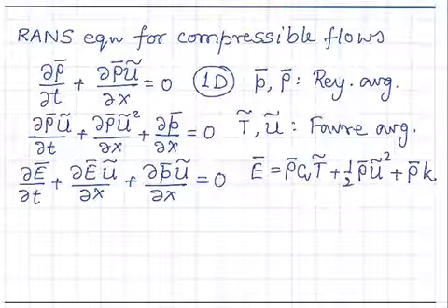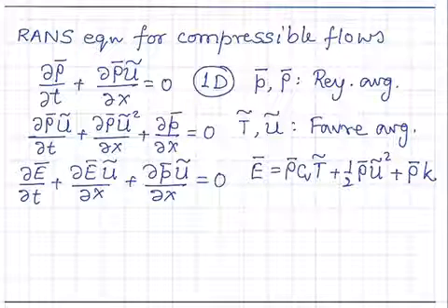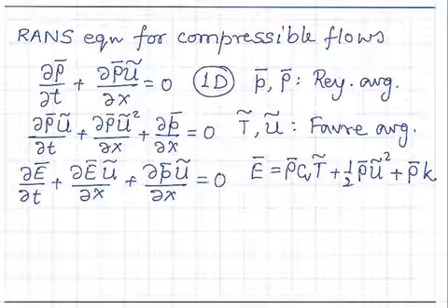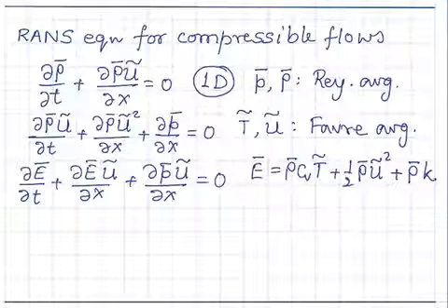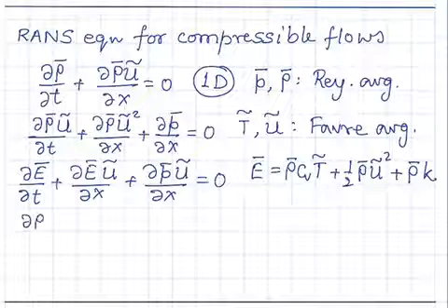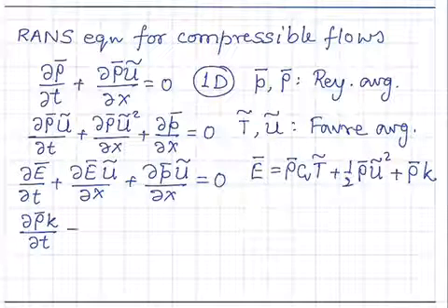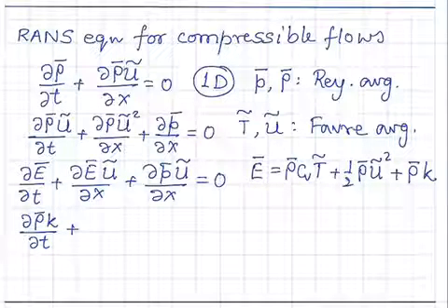Now we need to compute the turbulent quantities, which represent the turbulent fluctuations in the flow, and here we will adopt the K epsilon framework, for which we have an equation for K, or rho times K, time derivative.